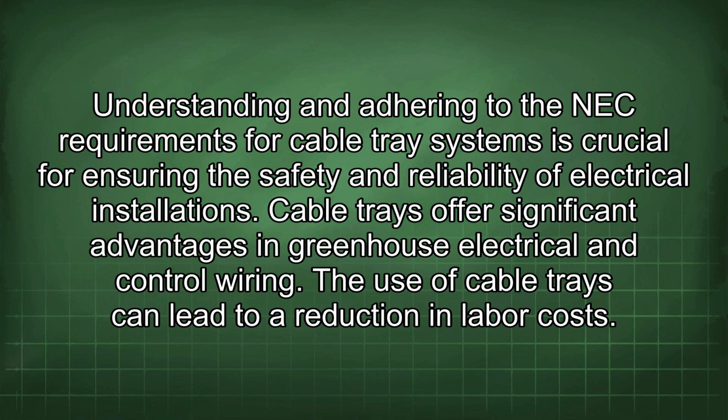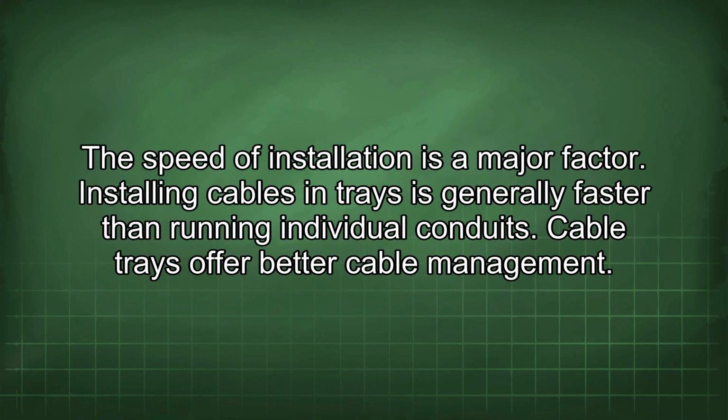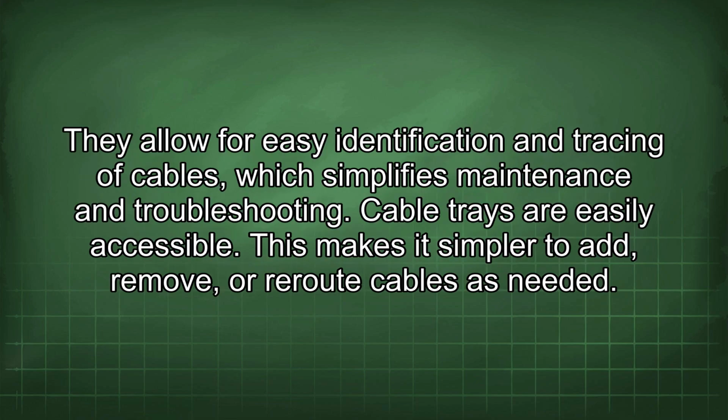The use of cable trays can lead to a reduction in labor costs. The speed of installation is a major factor. Installing cables in trays is generally faster than running individual conduits. Cable trays offer better cable management. They allow for easy identification and tracing of cables, which simplifies maintenance and troubleshooting.